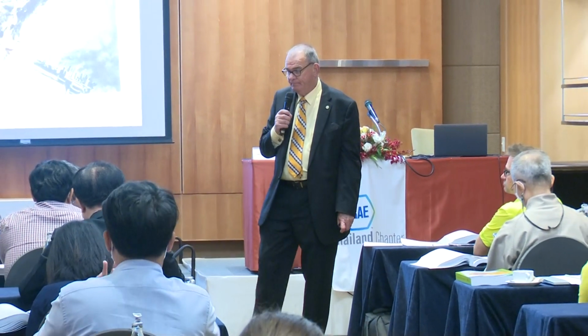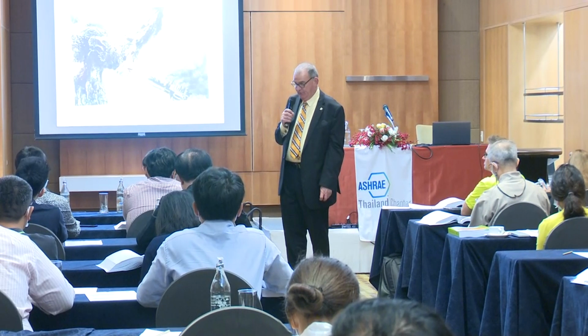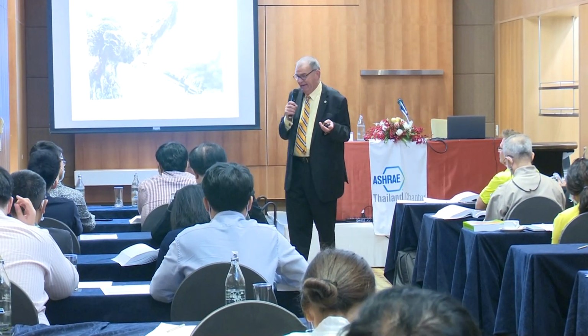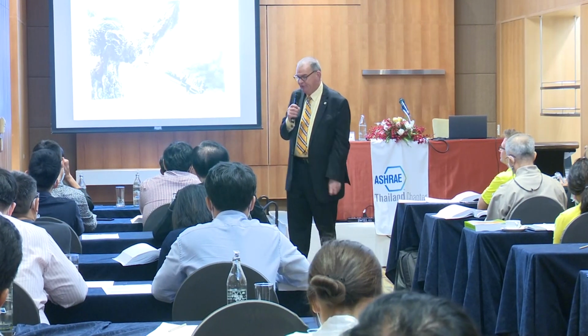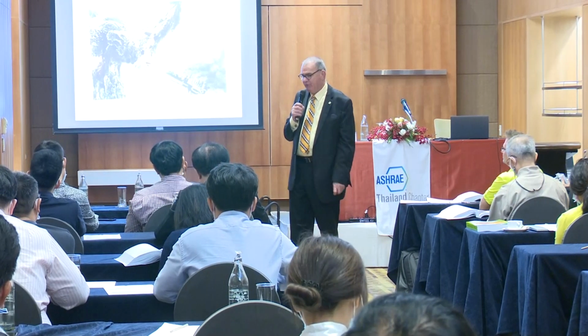You measure only one number, but at different locations. Different locations, exactly. And again, like in that example, you end up with 50 or 48 locations. So you have to average those 48 locations to get your average velocity.